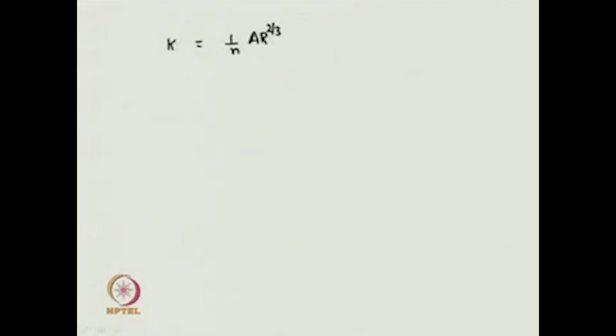For the upstream compound section or normal simple section, whatever it may be, you evaluate the corresponding conveyance factor. In the downstream of the reach, you also need to take into account the conveyance factor. Now, for the entire reach, the second step is to obtain the average conveyance factor for the entire reach.